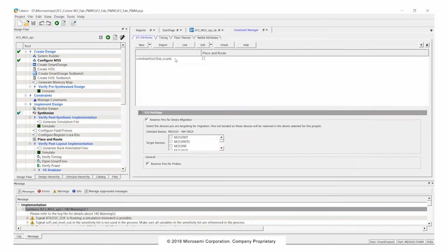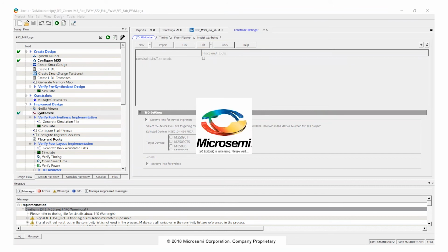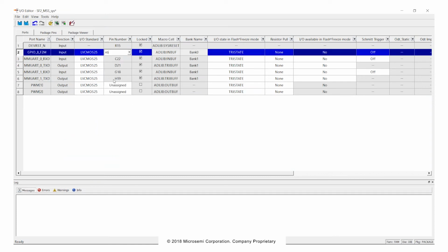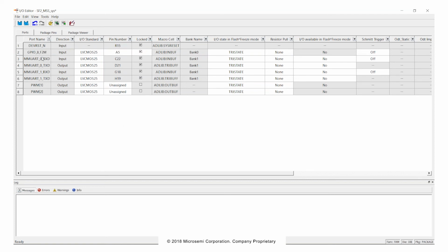I could save that. We'll see it on the constraint manager here. So it'll show up. Now, when I put something on the constraint manager, if I don't check it, it's not actually going to be used. Also, if you right click on a constraint, you see you have some various different options here, and one option is set as target. What that means is, if you set a file as the target, you'll see it say that it's the target, and any changes you make in other tools, for instance if I open a graphical tool, would be made in the file that's set as the target. If I don't set a file as the target, then it would create a separate file.